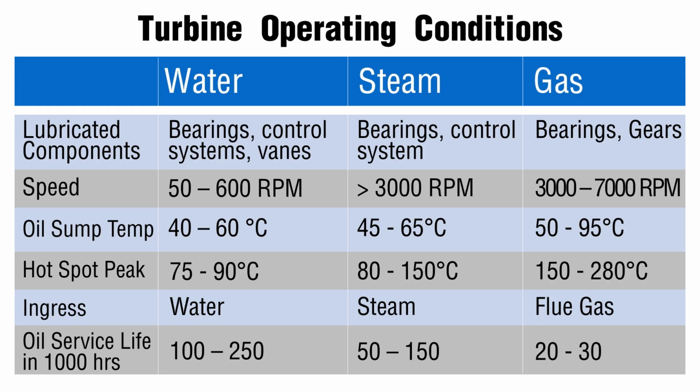At the same time, the base oils should have good solubility with the additives used so as to ensure good filterability of the oil. Turbines having gearbox need anti-wear and extreme pressure additives which protect the gear, at the same time taking care not to corrode the yellow metals like copper, brass and bronze.